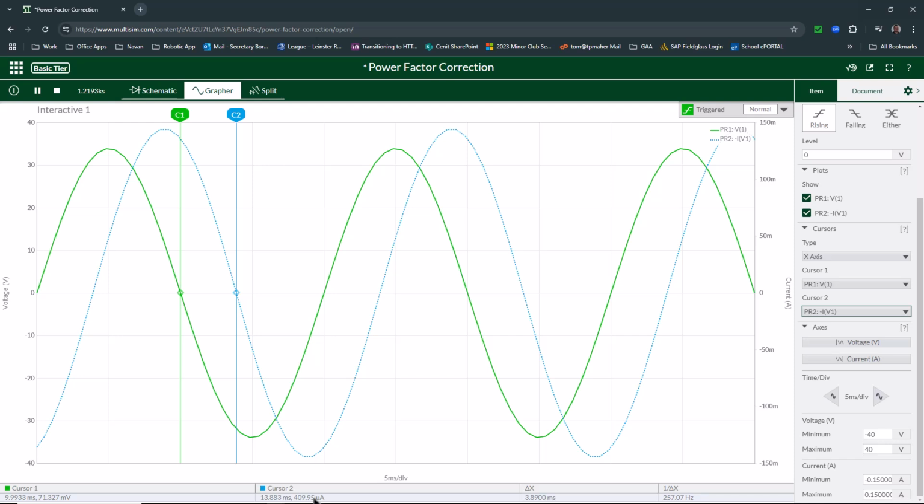What I mean by that is we've got plus 71 millivolts there on the voltage, so we should be on plus on the current. Otherwise we're opening that gap a little bit more, so we want to stay on the same side of 0, so either two negatives or two positives. Now, let's say on the current one here, the closest I can get to is minus 50 microamps. That's a good bit closer than the 400. In that case it might be worthwhile to have a positive and negative, but in general we want two positives or two negatives.